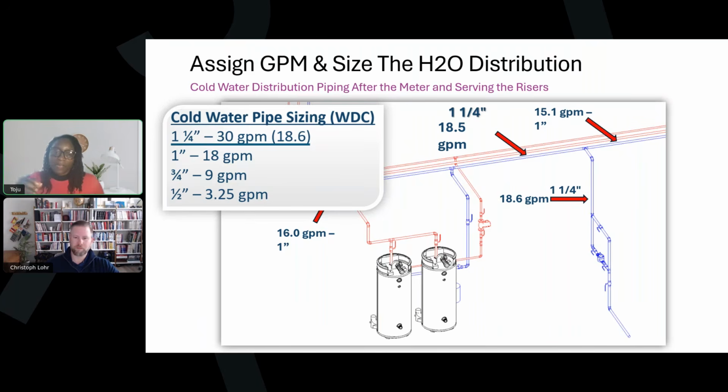So the change in the demand flow rate is not necessarily linear or assigned to one particular fixture, because we're looking at the combination of all the fixtures and then the 99th percentile. There's a whole lot of statistics and calculations that went into this, and because of the p-values and the corresponding flow rates, these are the 99th percentile that we are getting with very high confidence.